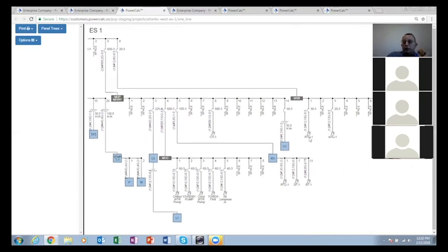Remember, it was only rooftop unit number 1, and we just connected air handling unit number 1 to it. And here it is with all the parameters that support that particular load. Now, the same method can be used if you decide to say, you know what, no, MSB does not feed air handling unit number 1. Actually, air handling unit number 1 is fed from MCC.